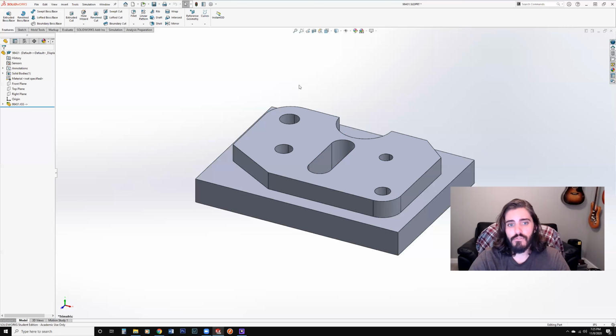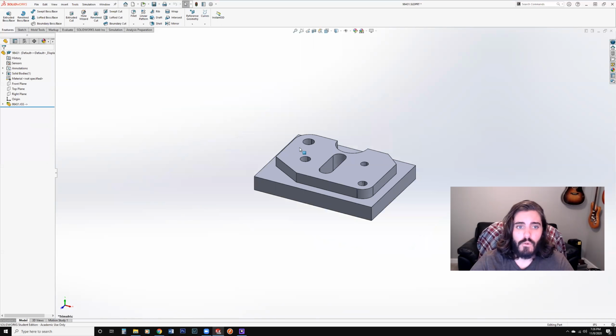So I hope this was helpful in looking at this from a perspective of, again, creating a 2D drawing from a part, creating a DXF or DWG transfer file from a drawing. You can also create a PDF from that file format as well, and then also sending 3D files either from an IGES file, a Parasolid file, or a STEP file. So just take that again with a grain of salt, and hopefully that helps you along your way transferring files.